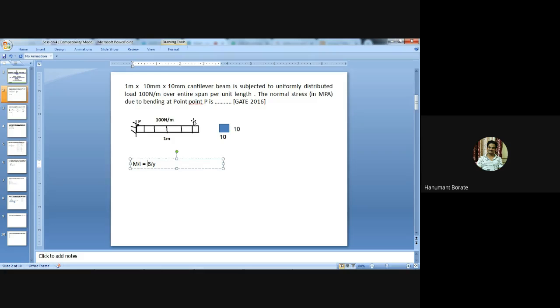Okay, so first we will see what is meant by bending stress and shearing stress. Due to external loading, the beam tends to bend. Generally, whenever a load is a transverse loading, due to external loading the beam tends to bend or deflect, and internal stresses resist its bending. The process of bending stops when every cross section sets up full resistance to the bending moment.